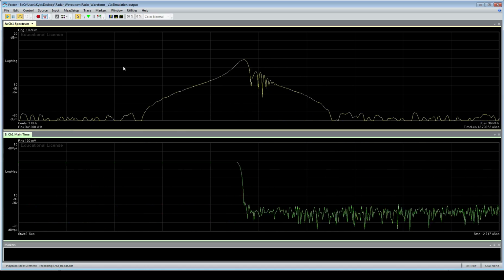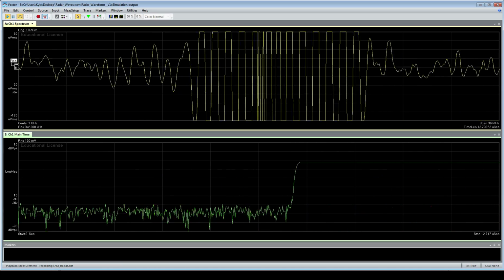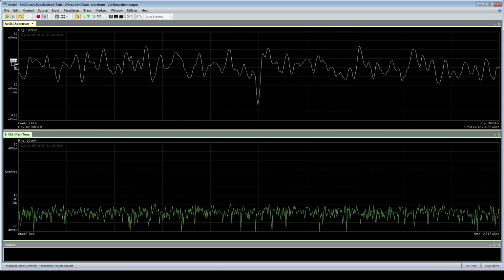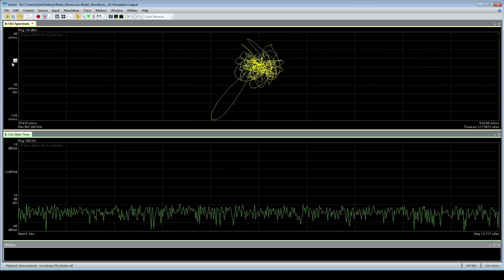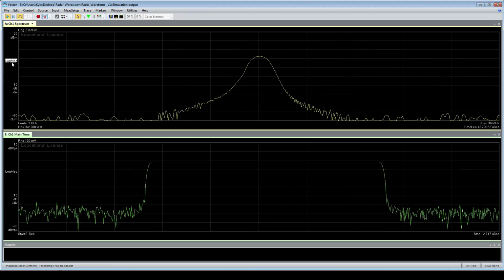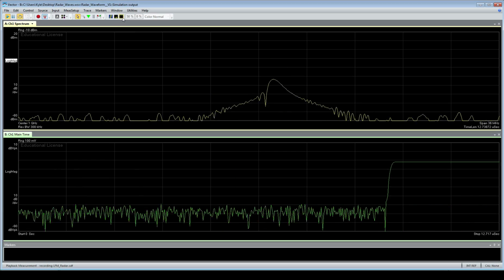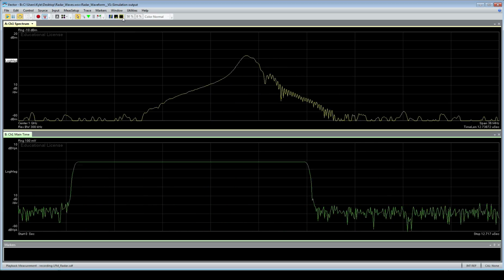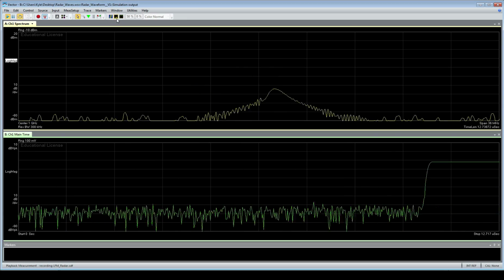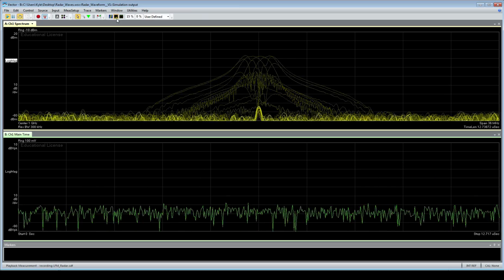So the first thing with the spectrum, we can change over here. If I left click and then scroll my mouse key up and down, I can actually see a bunch of stuff. I can change to a linear magnitude plot, real, imaginary, a phase of my spectrum, I and Q, constellation, so on and so forth. But we are going to stick with the straight up old log magnitude plot. And we've got a few options even inside that. So you can see at the top here where my mouse is right now, I have 3 options. The first one is show digital persistence. And there it's going to maintain some history, so we can see the spectrum as it changes.